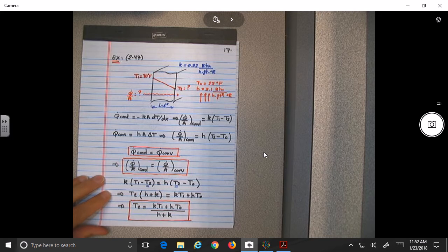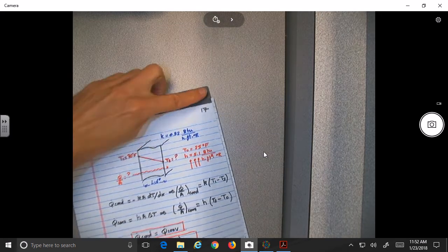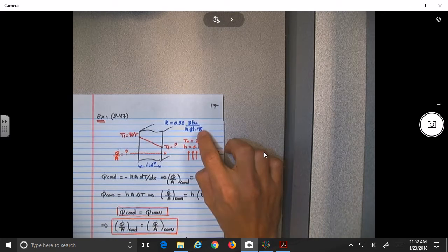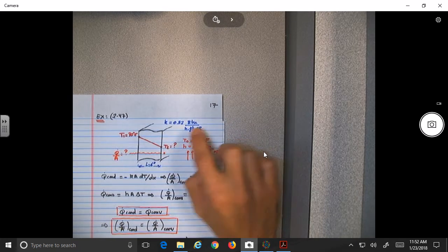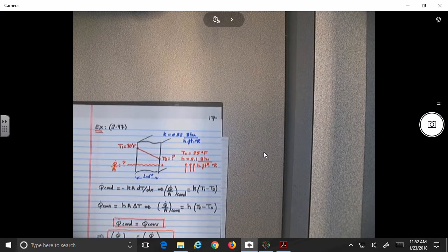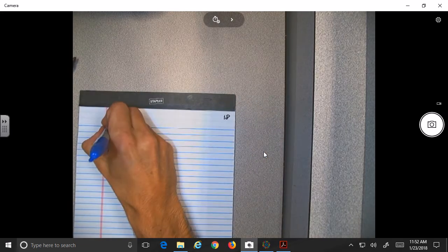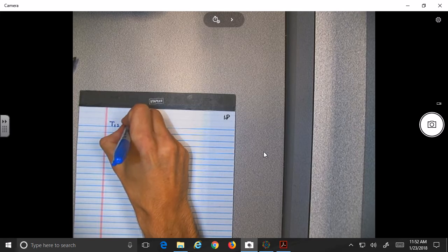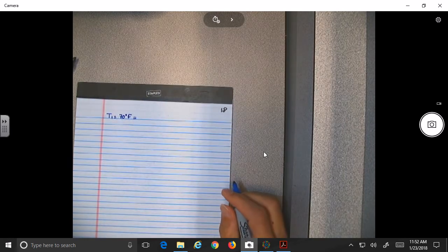All right, so let's see what will be the numerical application. Be careful over here, because if you look at K, what are the units of temperature for K? Rankine. So we need to move this one to Rankine, no? So let's do that first. T1 equal to 70 degrees Fahrenheit will be equal to how many Rankines? What did we say was the unit transformation?